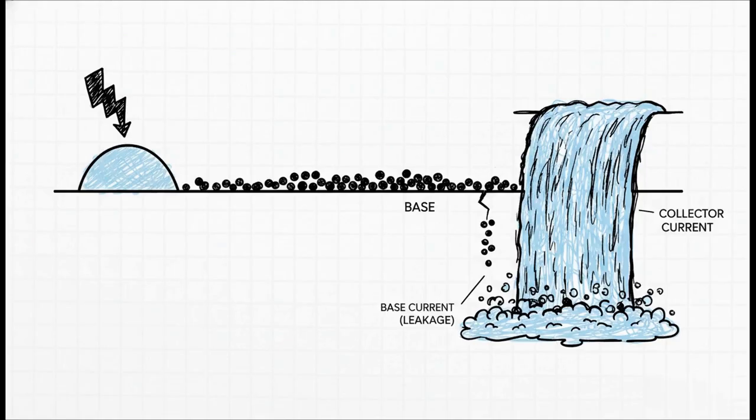2, now that the hill is smaller, a massive flood of electrons can easily diffuse across from the emitter into the base. 3, because that base is so incredibly thin, most of those electrons very quickly wander over to the edge of that base collector waterfall and get swept down into the collector. That's your collector current. And that tiny base current, that's just the few unlucky electrons that happen to bump into a hole and recombine before they can make it to the waterfall. It's a consequence, a side effect, not the cause.